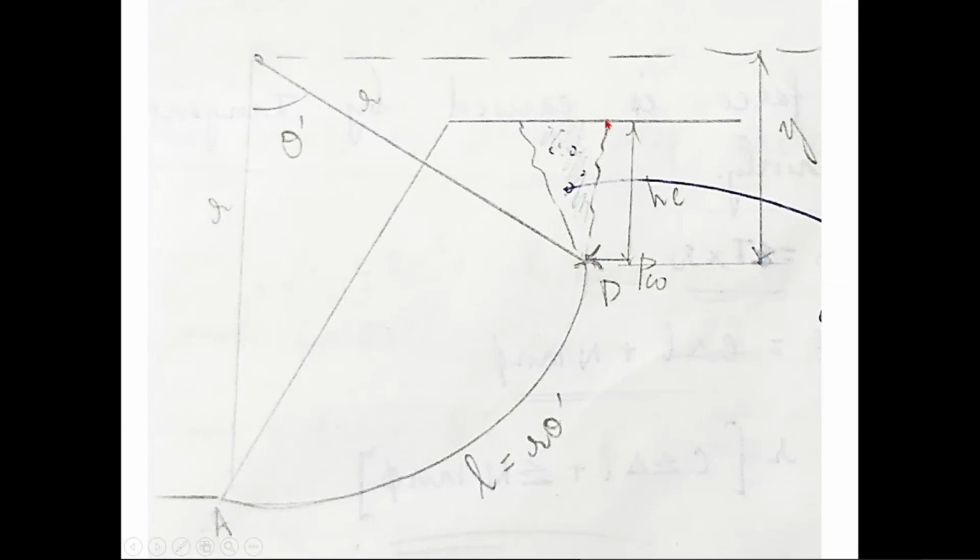From the point D to the ground surface, cohesion is not going to mobilize, and that is not going to resist any of this slope movement, right? So the cohesion will only be mobilized along the distance AD, correct?